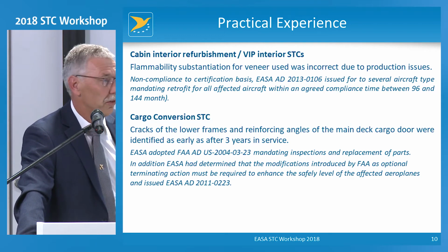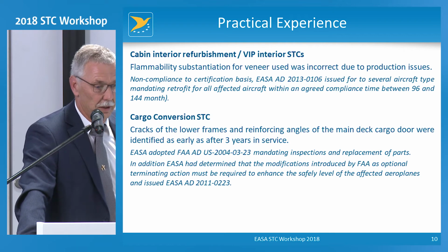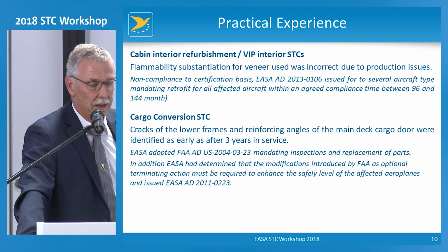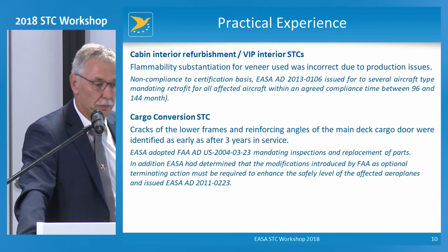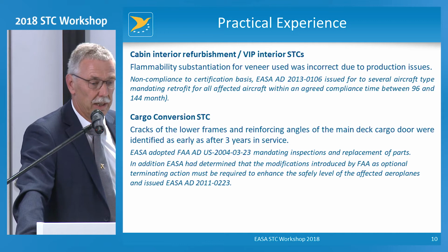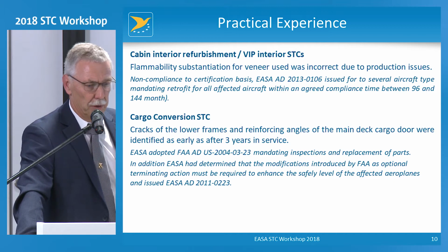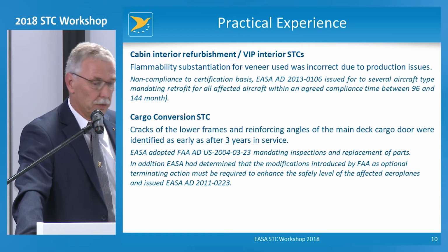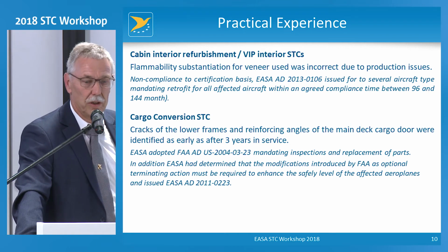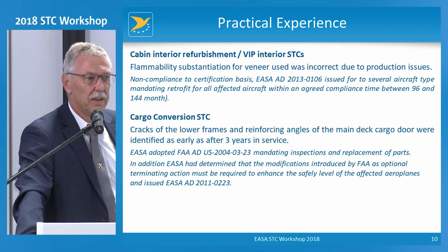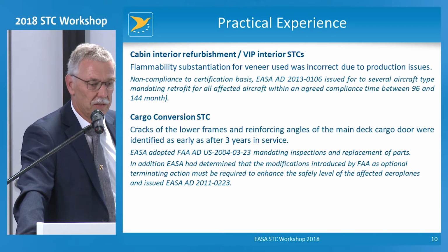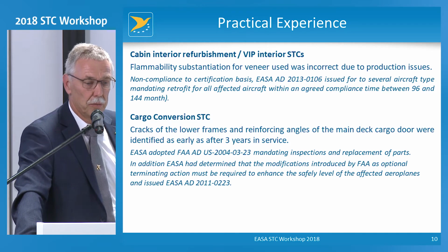Cargo conversion, this was an STC where I was involved when I was working early at EASA, and it's an American STC where even after 3 years there were cracks in the structure of the cargo door frames, and there were FAA ADs which we adopted, but then at the very end the repetitive inspections and the replacement could be terminated by optional terminating action, a better design that the FAA allowed to be optional, but EASA decided that this needs to be implemented on all the affected aircraft for operation in Europe.